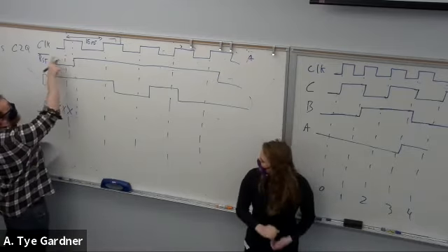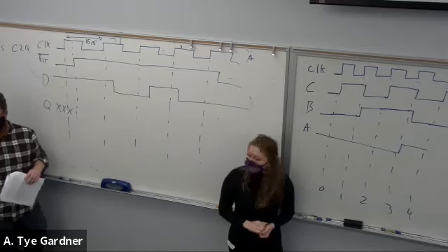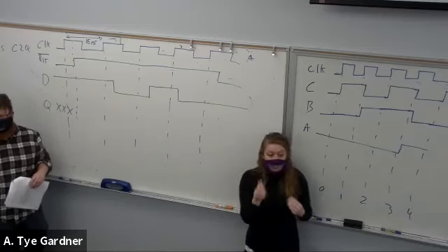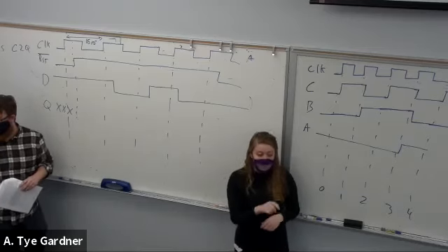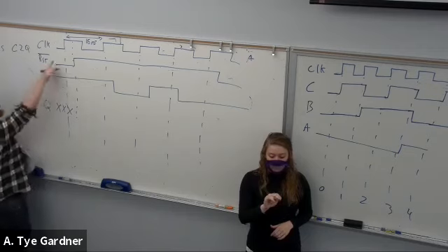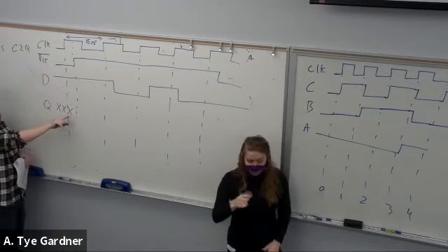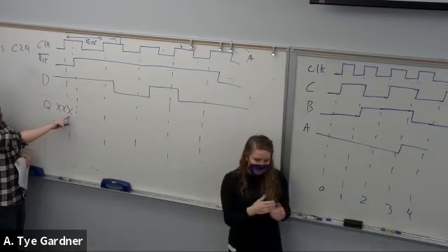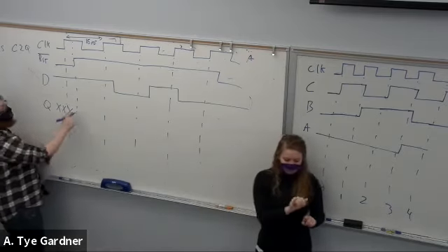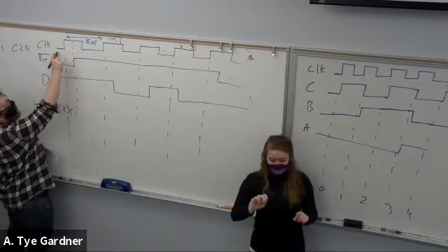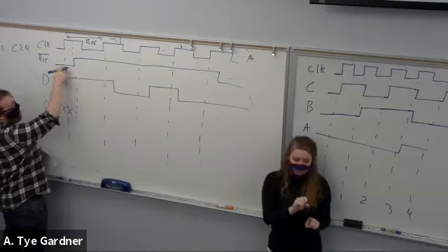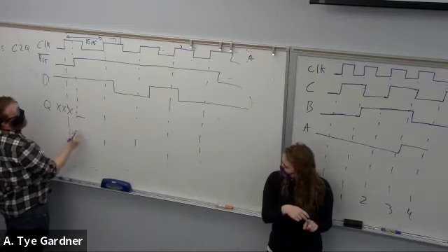If I had thought this question out, I would say that it is an active low synchronous reset. Right? Because if it was an asynchronous reset, then we already know it's 0, regardless of the clock. Everyone remember synchronous and asynchronous resets? Okay. So now because I have a rising edge of a clock, active low reset, I get a 0.